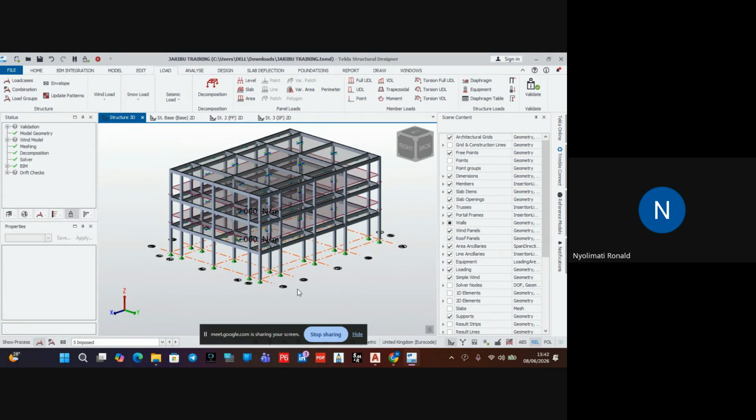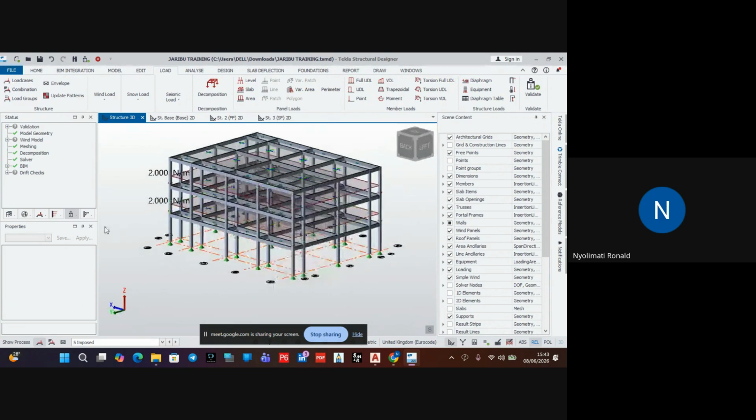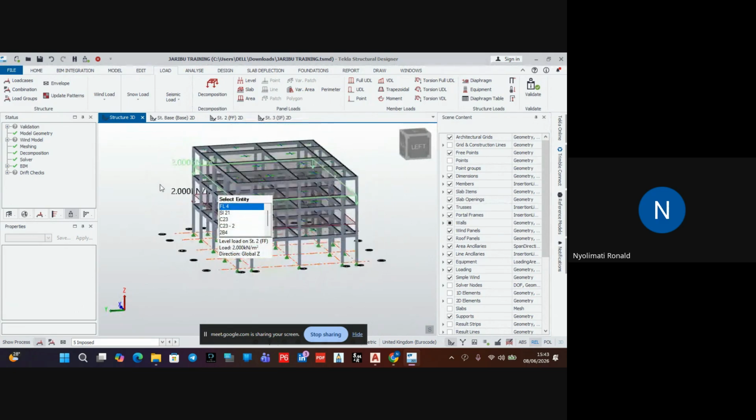If a church has like 300 people, you multiply by what one person carries, like 0.2, something like that. You may find it is going to have much more loading compared to the residential one. That's why it's being given different values.